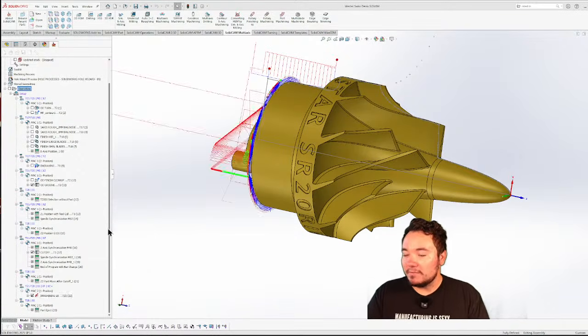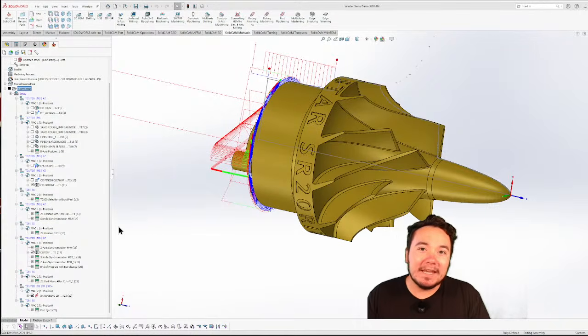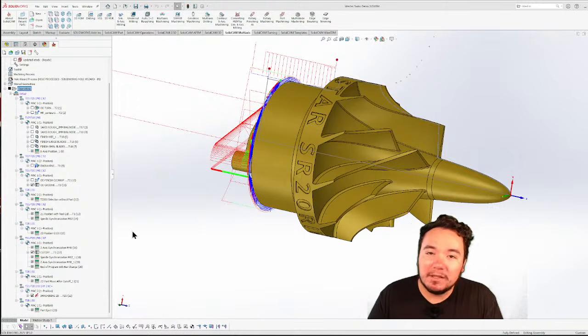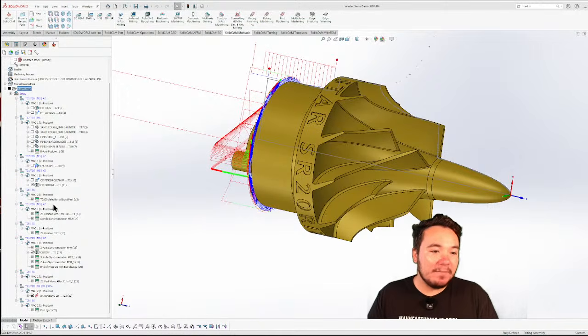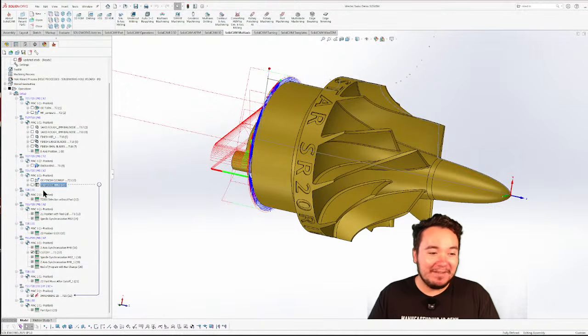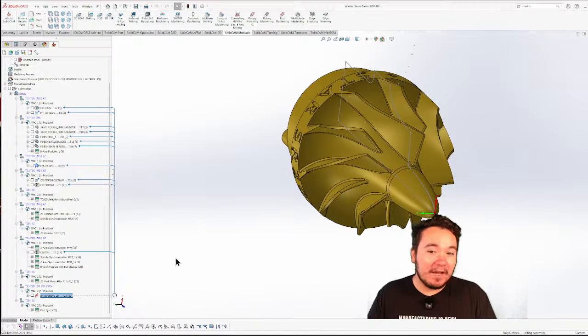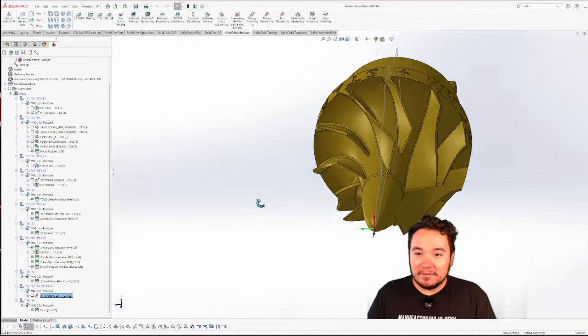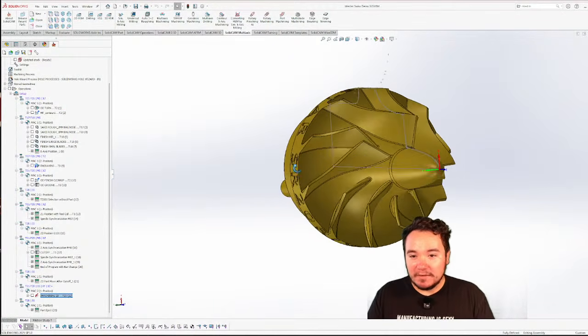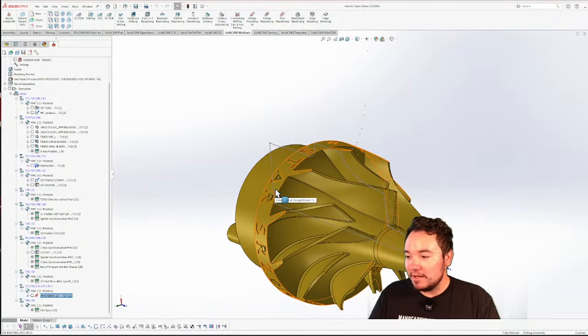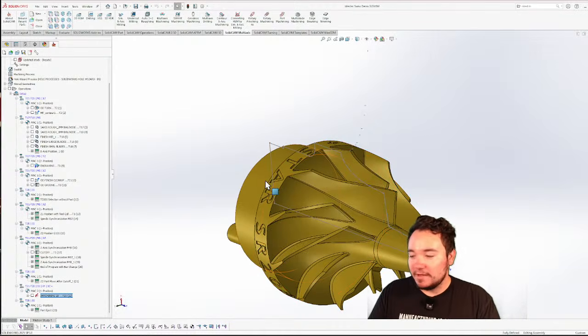Yeah, we just used it because it was easy to get ball end mills. I do see a lot of people using the lollipop end mills, but we just did it for the sake of cheap and easy to program with. The program looked fine with the ball end mill, and that's just what we decided to use on it. But I have seen a bunch of people use the lollipop style end mills. So you can go either way.